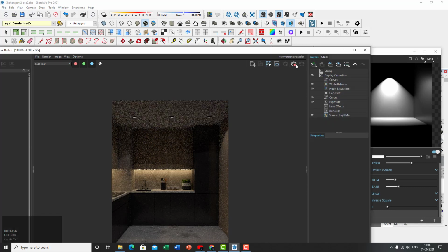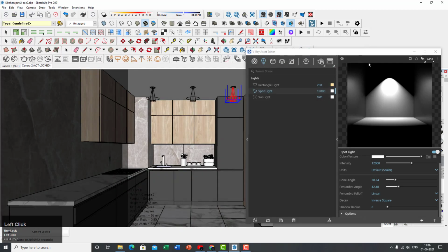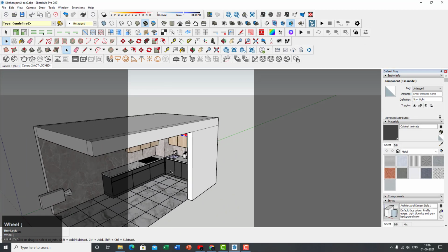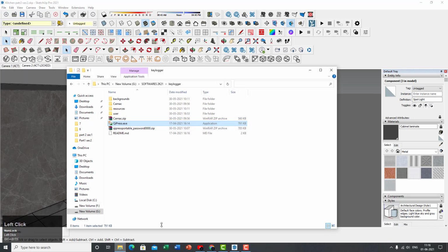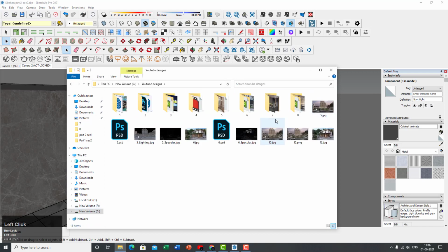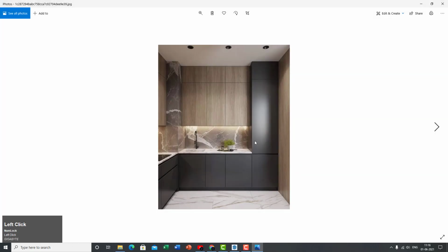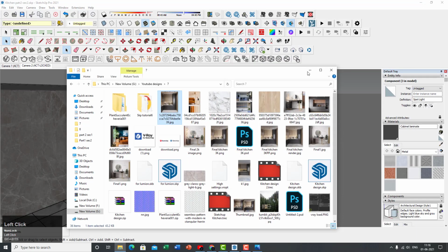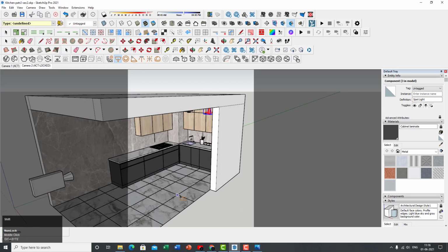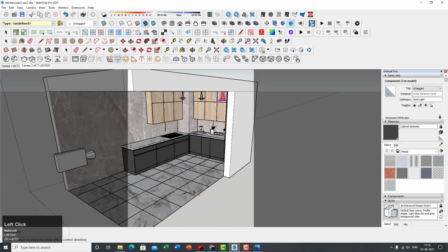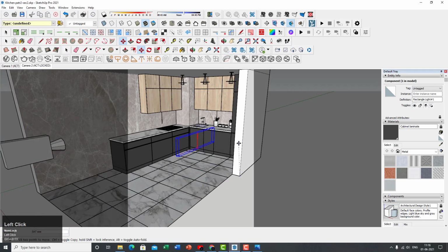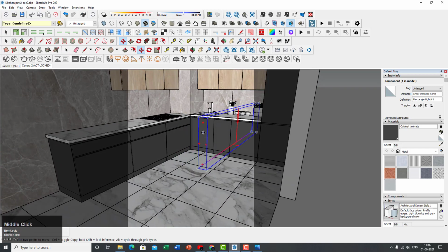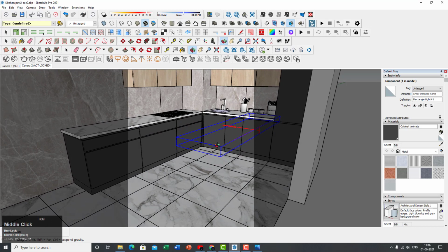In order to do that, switch off the interactive render again, close that. Now you're going to place another plain light in order to light up the room and replicate the shadow, the reflection that I was talking about, which is this. So let's do that. So click on plain light again, just draw a random plain light, select that, push that up there, rotate that.